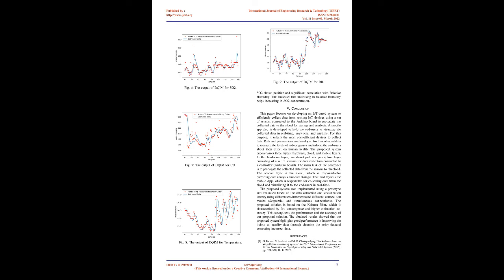During the tuning process, RMSD, root mean square deviation, is computed between the predicted value x produced by the KF and its corresponding actual value x collected by sensors, as given by equation 13. When the state of the KF is non-converged, the RMSD will be relatively large between the predicted value x and the actual value x. Therefore, the RMSDs for CO2, CO, SO2, together with temperature and relative humidity values, respectively, are normalized by the min-max normalization method ranging between 0 and 1.